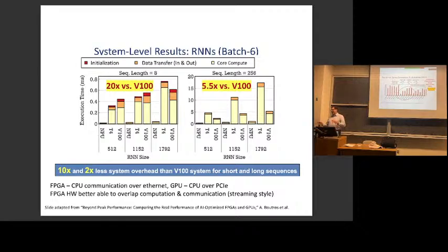That's why I don't think there'll ever be one overlay architecture that's going to go in FPGAs, because it's too generic. That overlay architecture will start degenerating towards something that's too close to a CPU or a GPU. And if you get too close to either of those, in my opinion, the extra programmability overhead you have makes it less interesting. There are still people who do that, right? There are researchers out there making soft GPUs for FPGAs. So I'm giving you my own opinion that I don't think it's the best idea, right? But there are other people who disagree with me. I think you have to customize more to the application.